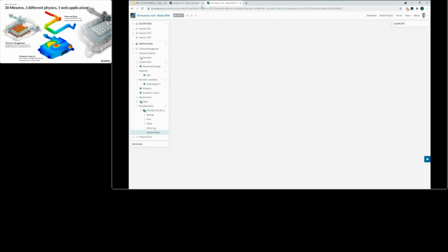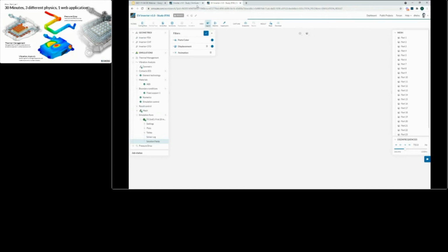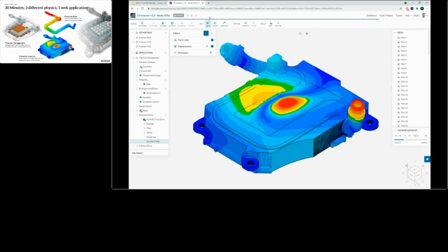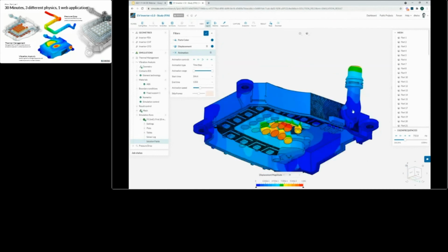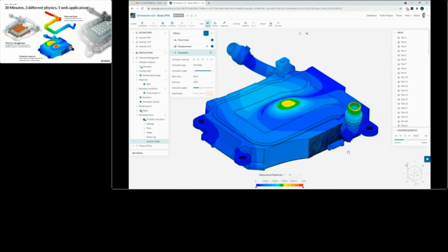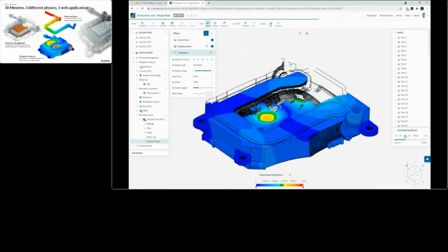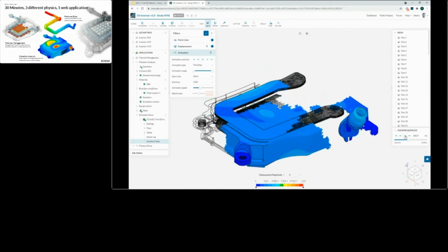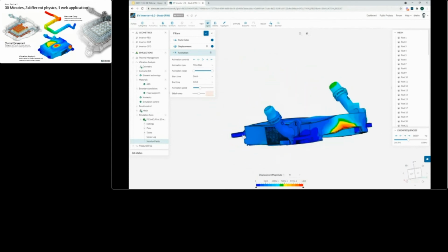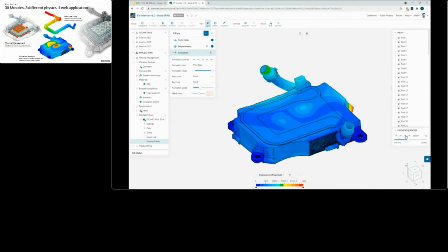And so we want to now take a look at the modes, at the eigenmodes and eigenfrequencies that were computed. So we're looking at the normalized displacement. In this case, we can see this is at 715 hertz. And as you're used to from frequency analysis, you can now step through the different frequencies where eigenfrequencies appear.